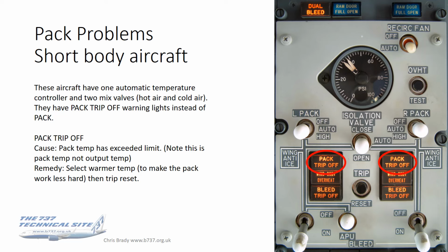So with that knowledge, you can see that the remedy for a pack trip-off would actually be to select a warmer temperature to make the pack work less hard. Then after a minute or so's cooling, press the trip reset, and bingo, you should have your packs back available to you.